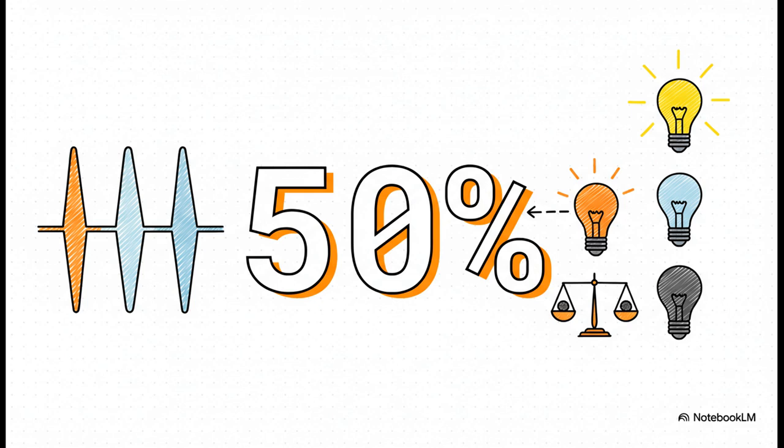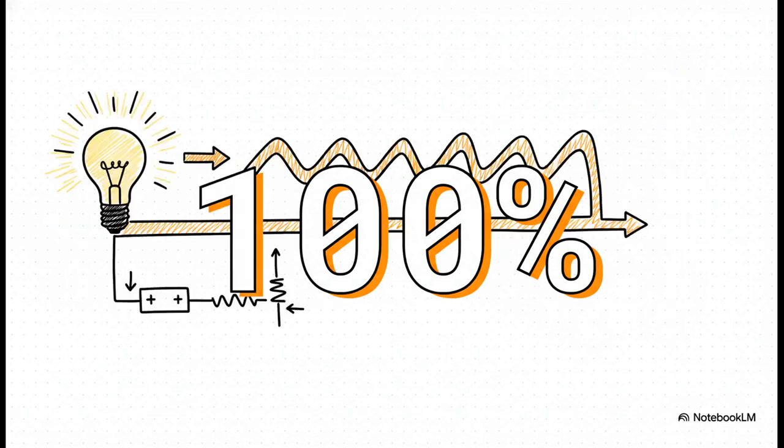The power is on for half the time and off for half the time. So what you get is exactly half of the total possible power, which gives you a nice, medium brightness. And at 100%, well, that's easy. There's no off time at all. The signal is just constantly on, full blast. This is exactly the same as just hooking the LEDs straight up to the power source. It's getting all the juice, so it's at maximum brightness.